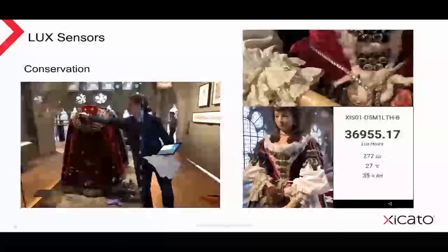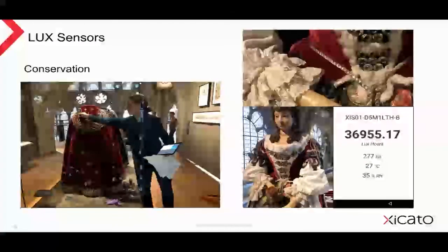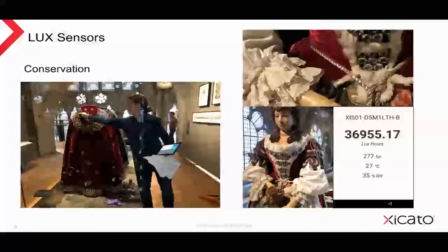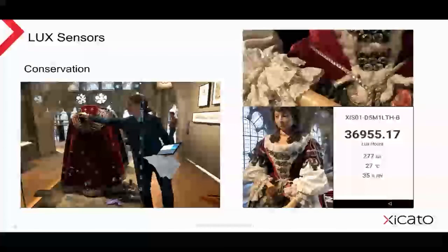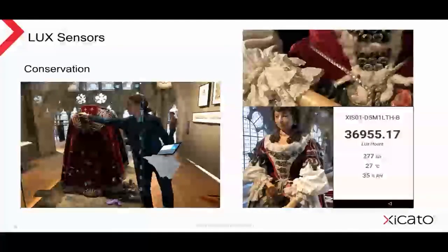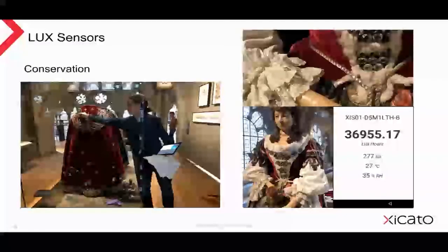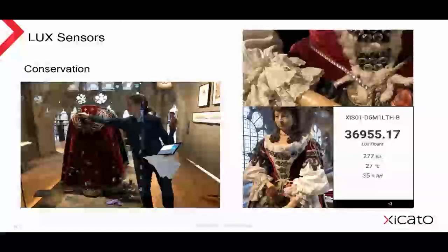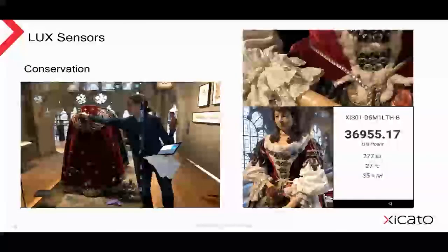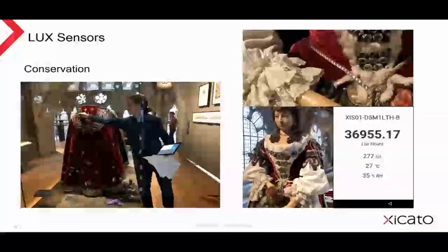There's also lux sensing. Artificial lighting is dimmed or even switched off if there's enough natural light to retain the designed illumination level, let's say 50 lux. With the hierarchy of commands, presence detection comes first. If there's no one present, the lighting is off. But when it's on, it's tempered by daylight ingress. In the picture, you see the lighting designer, Peter Foreman from DHA Designs, measuring the lux levels on an exhibit. In the next slide, I will show you a simplified screenshot of a control panel showing how this is done.